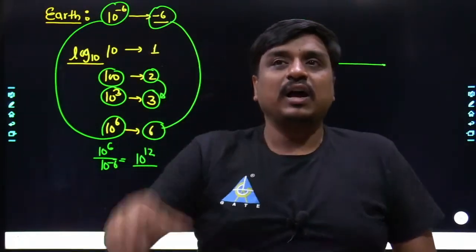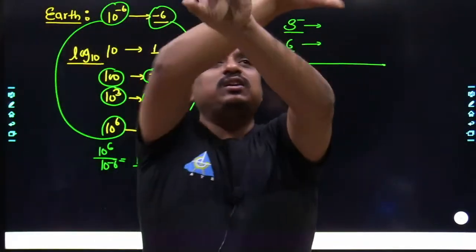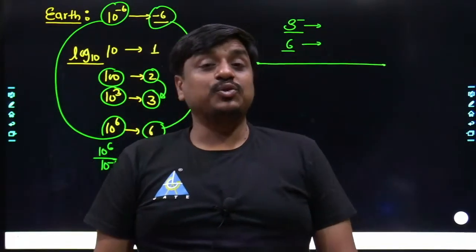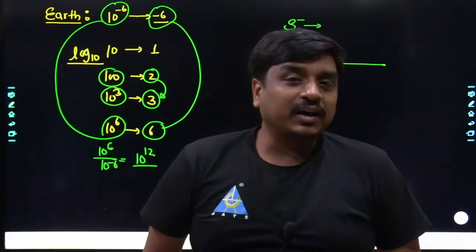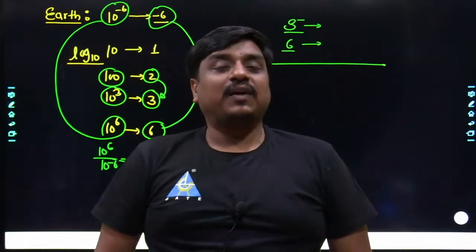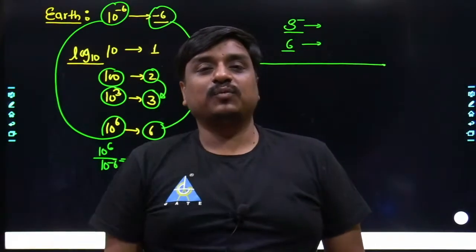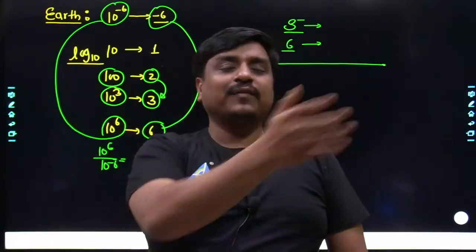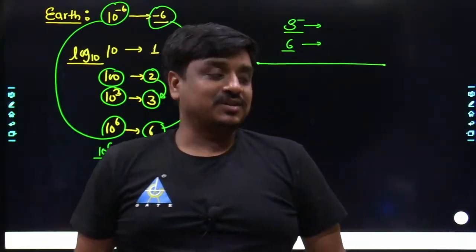So what I used to do is take the magnitude here and here. Similarly, on the denominator side, I take the magnitude separately, and in the end I apply the logarithm, and once we apply it, all of the multiplication gets converted into addition, and all of the division gets converted into subtraction.